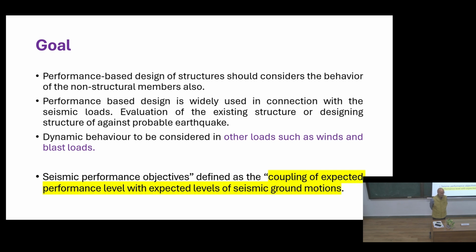Suppose you talk about a building. What could the possible things be? Window. Okay. But the location of the window is very important. When you do seismic design, the location of the window is very important. Opening, rather, I would say. Opening is a very important placement in the entire structure. So that is at design level. You incorporate it at design level itself.